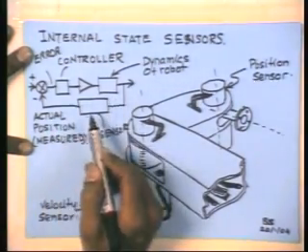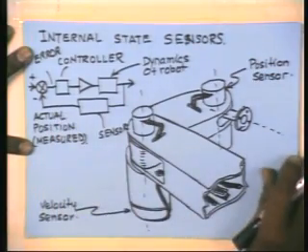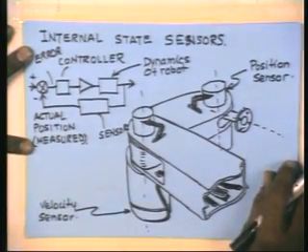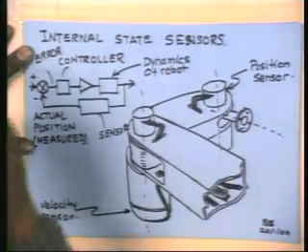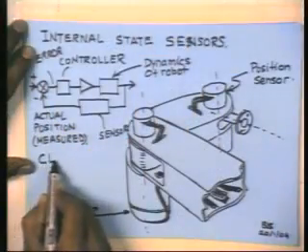If it's velocity that you're trying to control, because there are tasks in which you will need to control the velocity. One example would be if you had a conveyor on which some part was going, and you wanted to take the robot and pick up the part from a moving conveyor. In that case, you will have to choose a trajectory which will come to the part, align with it, then move along it, and then pick it up as it's moving along. So velocity control becomes very important. So this is the kind of loop that we are talking about. This is basically a closed loop system.